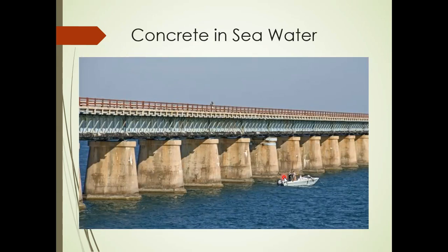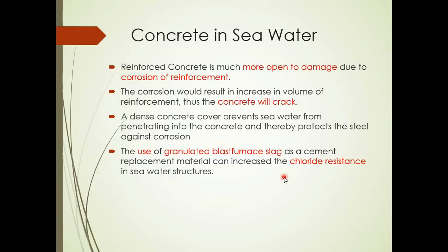For example, let's say you are going to build bridges in the seawater, then we need to take care of the durability of the concrete by increasing the density. Reinforced concrete is much more open to damage due to corrosion of the reinforcement. The corrosion will result in an increase in volume of the reinforcement, thus the concrete will crack.